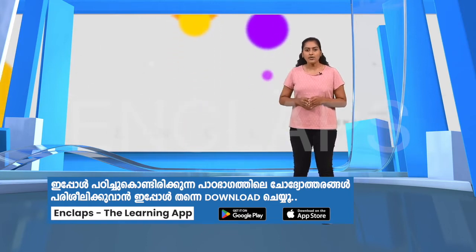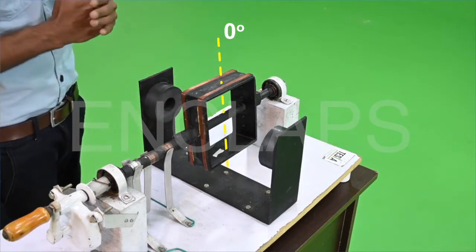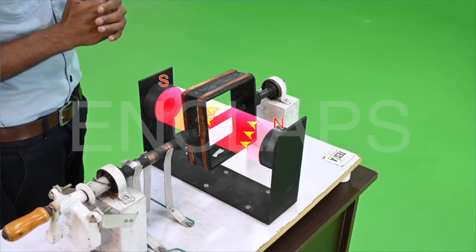Let's see how an AC generator works. This is the 0-degree position of the armature coil. We know that the magnetic field lines are from north pole to south pole. In this position, the magnetic field lines are parallel to the armature coil and hence field lines are passing through the armature without getting interrupted. So, there is no change in flux and hence the induced EMF and current is 0.